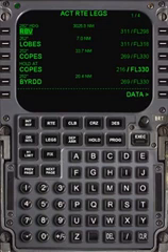The accuracy is described as the actual navigation performance (ANP), a circle that the aircraft can be anywhere within, measured as the diameter in nautical miles. Modern airspace has a set required navigation performance (RNP). The aircraft must have its ANP less than its RNP in order to operate in certain high-level airspace.